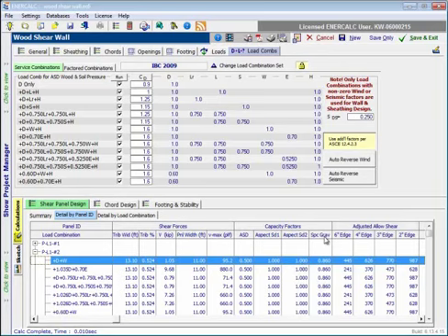And then the last capacity adjustment factor is one that's specified for the specific gravity of the framing. So remember, way back on the General tab, we selected the framing and chord material, which included a specific gravity. And then here, in accordance with the special design provisions for wind and seismic, we're making any necessary adjustment to the nominal shear capacities for the selected sheathing based on the specific gravity of the framing that the fasteners are penetrating into.